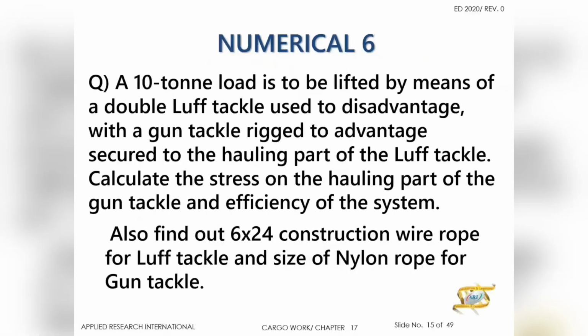First, I will calculate the effort of this double luff tackle. So I'm repeating. First, I will calculate the effort of the wire rope or of the hauling part of the double luff tackle, which will become load for the next gun tackle. Then, obviously, I'll find out the next effort, which I can name effort 2. So first, I'll find out effort 1, which becomes load for the next tackle, gun tackle over here, because that is where it is connected to the next tackle. Then I'll find out effort 2 and thereafter other things as required. That's what I'm going to do now in front of you.